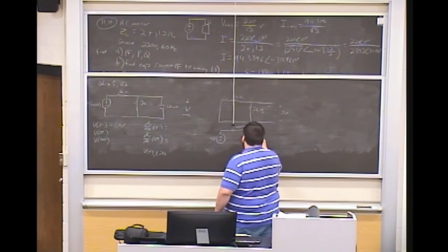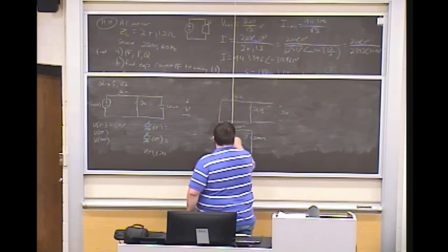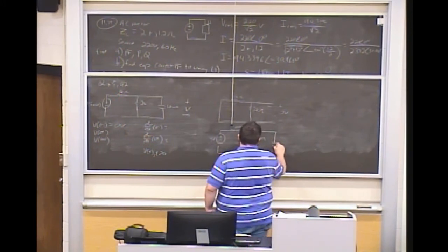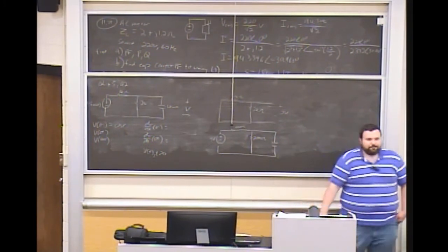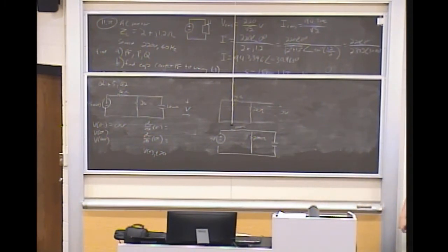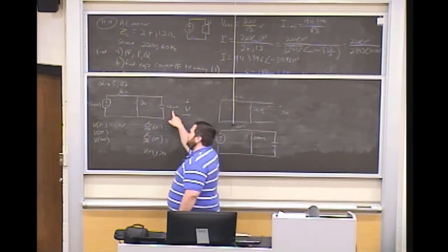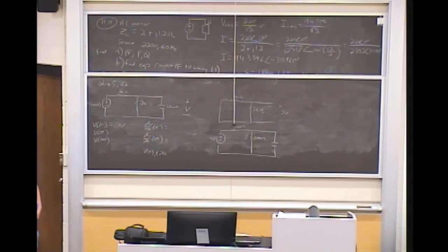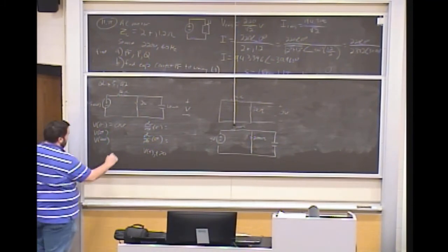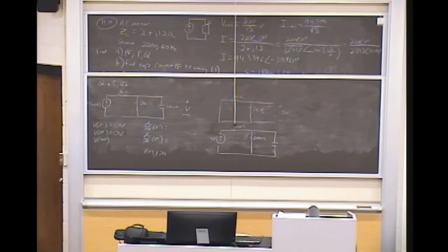We still have 2,000 ohms here. Now we have our capacitor. It's tempting to think that's a voltage divider. But what do we know about how capacitors behave with their voltage? They can't change stepwise instantaneously. So V at 0 plus also better be 0 volts.